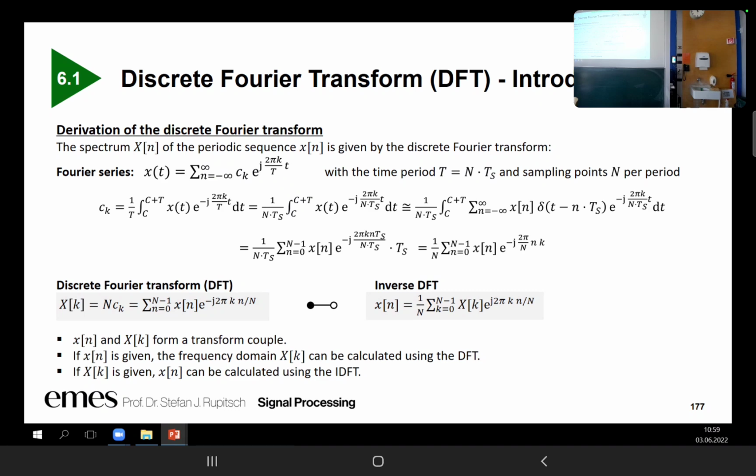We only take a look at the signal for a limited amount of time, and outside this time we assume that the signal gets repeated periodically. Only in doing so are we able to obtain a frequency-discrete spectrum. Otherwise, our spectrum will be continuous.